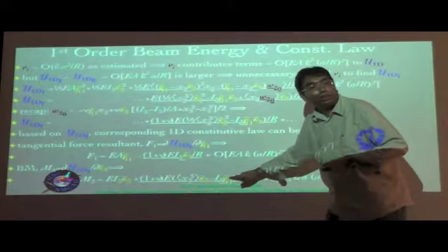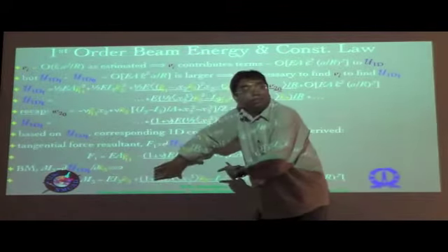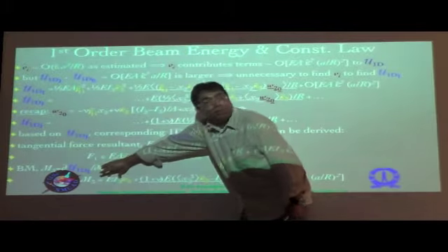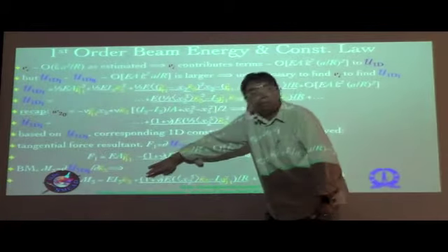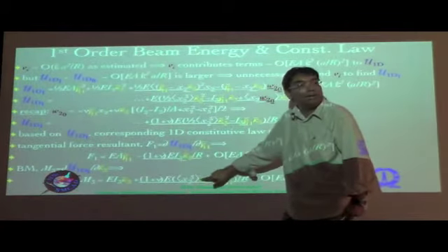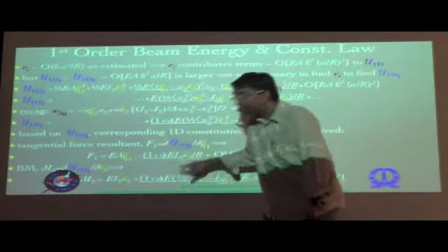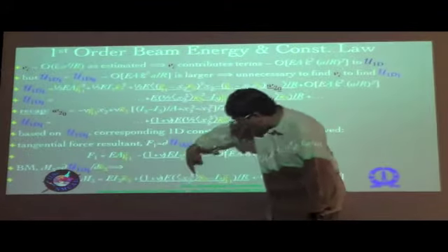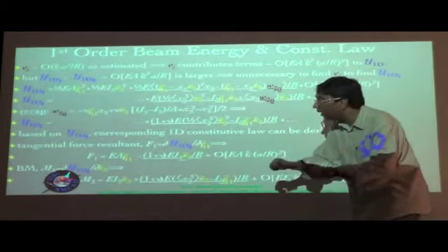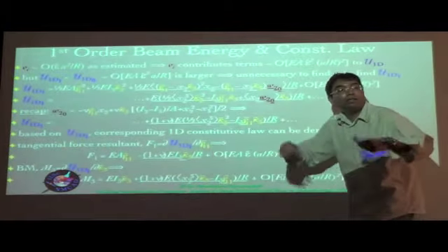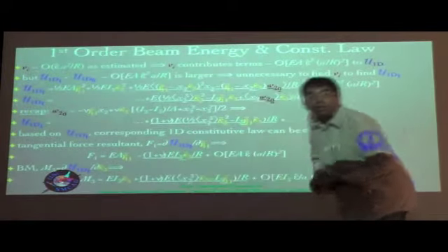That is one term, which is the coupling term, but you also see there is another term which is contributing to the bending stiffness itself. So in other words, EI3 alone is not the bending stiffness. There is an additional bending stiffness term which is contributed by this, because this is linear in kappa 3 bar. Just like this term is linear in kappa 3 bar, that is the bending stiffness, 0th order. There is a correction to that bending stiffness that also depends on the initial curvature. So the initial curvature can make the rod either more difficult or easier to bend, depending upon the sign of this.